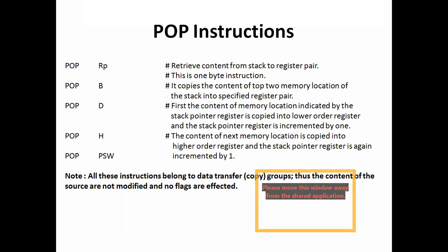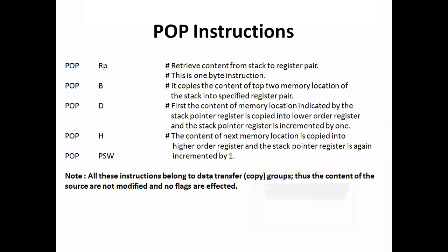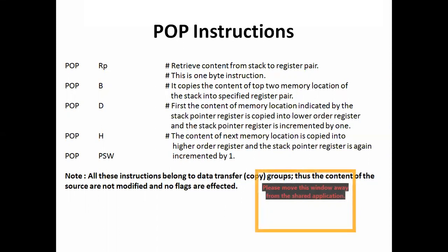In a push operation, first the stack pointer is decremented and then the copying is done. Again it is decremented and then copying is done. But in the pop operation, first the copying is done, and then the stack pointer is incremented by 1.